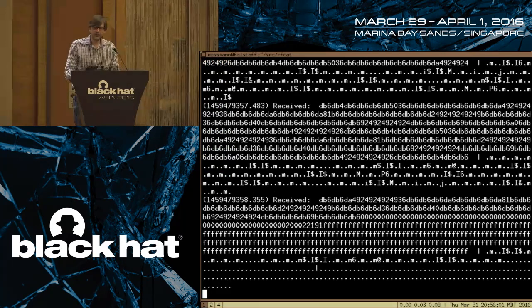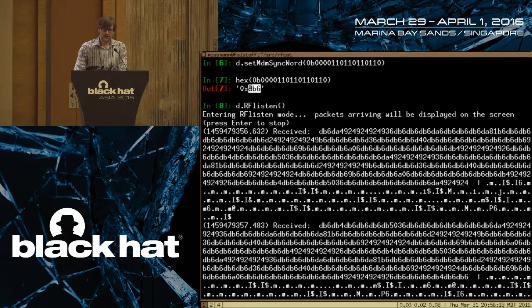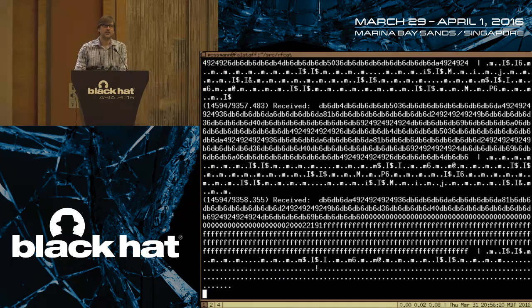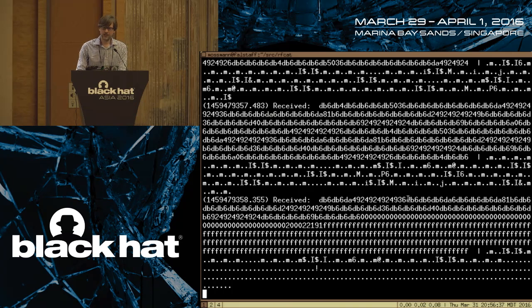Now we're getting something. Do you see how we get a lot of the same stuff over and over and over again? Like DB6, DB6. That's because if you think of those numbers in hexadecimal, DB6, that's what we set our preamble to. So every time you see DB6, that's part of the preamble, or a section of the packet that looks like a preamble. We're seeing a lot of repetition, which is interesting, and a bunch of stuff that happens every time I push a button.